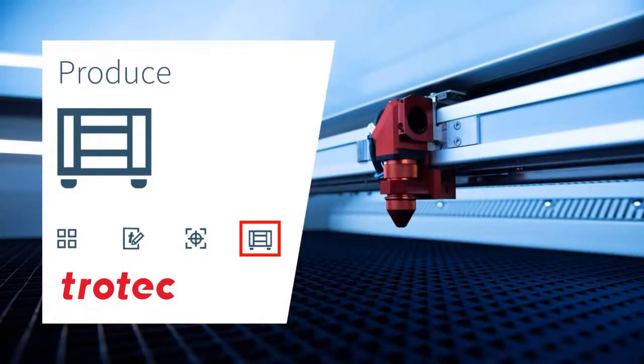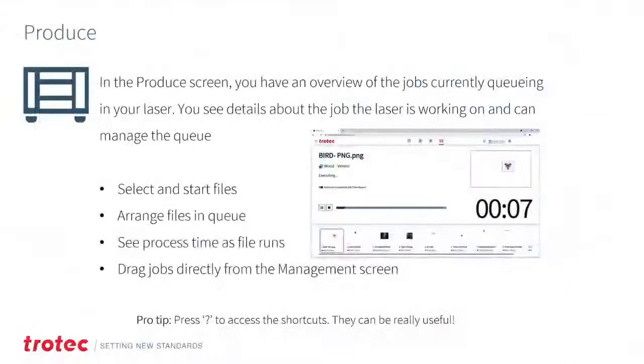Lastly, we have the Produce screen. In the Produce screen, you have an overview of all the jobs currently queuing in your laser. You see details about the job the laser is working on and can manage the queue. This screen will allow you to select and start files, arrange files in the queue, see process time as files run. It is also possible to drag jobs directly from the management screen for faster production operation.